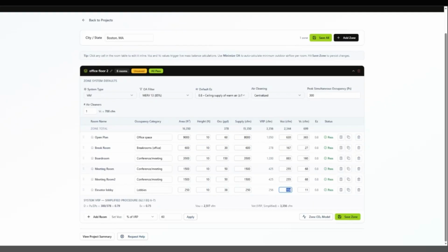So I'm going to make this 75 CFM, for instance. And I guess what I'm demonstrating here is that you can also individually allocate airflow if you wanted to. And again, this will have everything to do with the way you duct your system. All of these results, hit save, let's make sure everything passes. All of these results pass.